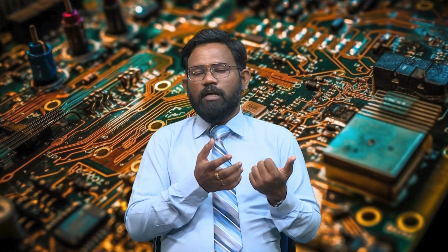So, in this way we have seen the working of dual or combination clippers, in which we can change, modify or clip the voltage in both the halves, which is not possible with the series or shunt clippers, in which we can only clip either of the halves, either positive or negative. So, in this way we have studied the three types of clippers, that is the series, the shunt and the dual or combination clippers.